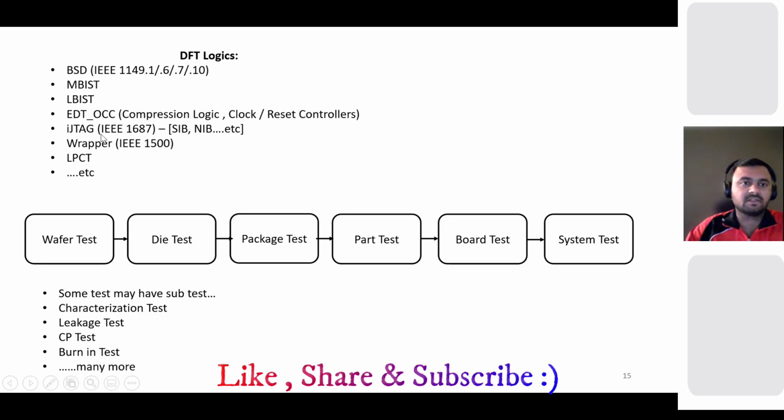You just keep it as an introduction. We have there a SIB and NIB, which we'll discuss. And we have wrappers, that is IEEE 1500 again. And then low pin count test, LPCT, is a methodology: if you have a pin-limited design and don't have that many pins to test with, then use LPCT. There are many more. So these are the basic major DFT logic we use to test the chip.